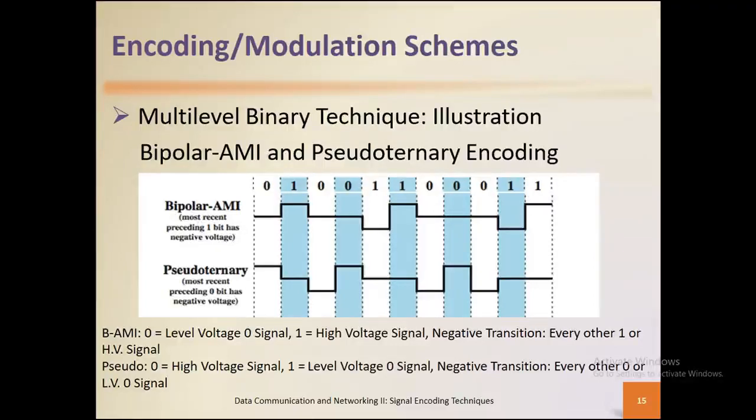Okay. So looking at this sequence, for instance, we had 0 1 0 0 1 1 0 0 0 1 1 1. Sorry, 1 1. So we mentioned that zeros are usually level voltage pulses, and ones are voltage pulses, and it applies to zeros across the board. All zeros are always level voltage, the indication of an absence of a voltage pulse. But the ones are the indication of voltage pulses, and they have to alternate between positive and negative.